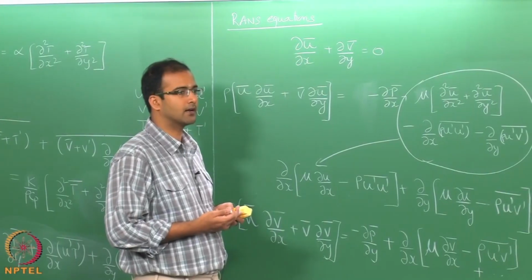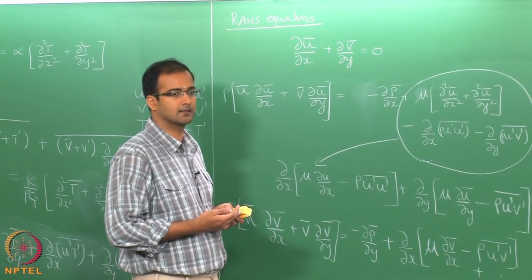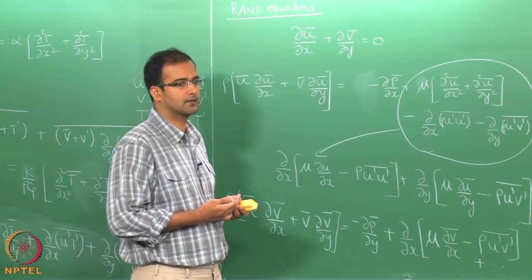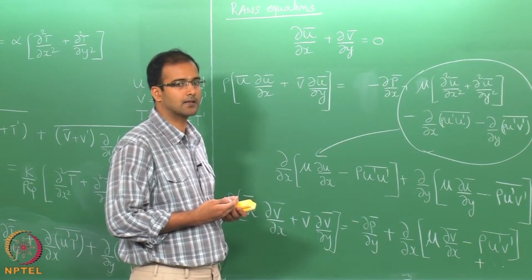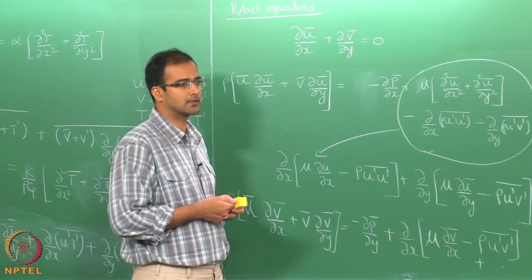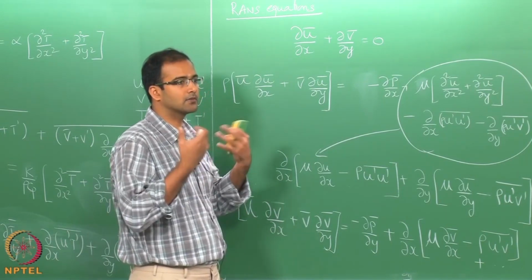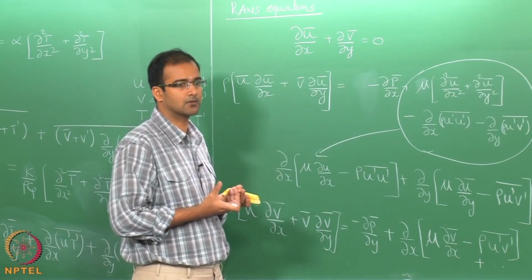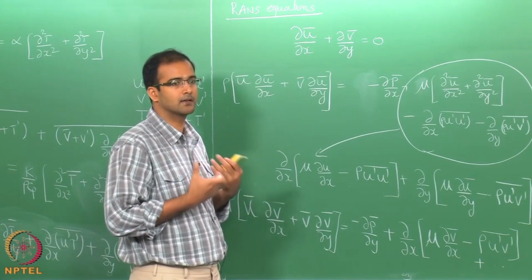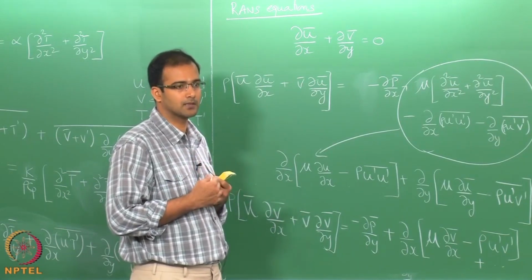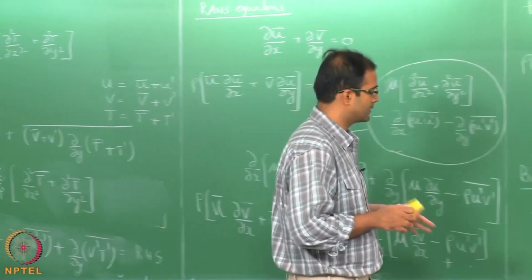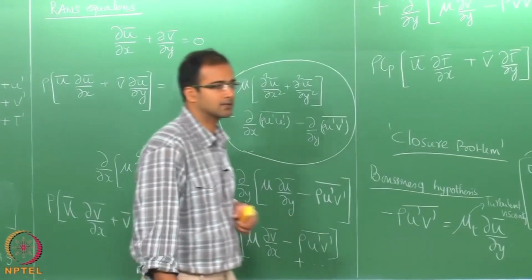Okay. So, I can now solve this equation using this analogy, but still what is unknown is the turbulent viscosity, and turbulent viscosity mu t is not a property, it is not a thermophysical property like laminar viscosity. So, again, it depends on the flow just like your heat transfer coefficient. So, for a given flow problem you have to actually understand how mu t has to be computed. So, for that we then solve additional equations and calculate the turbulent viscosity.